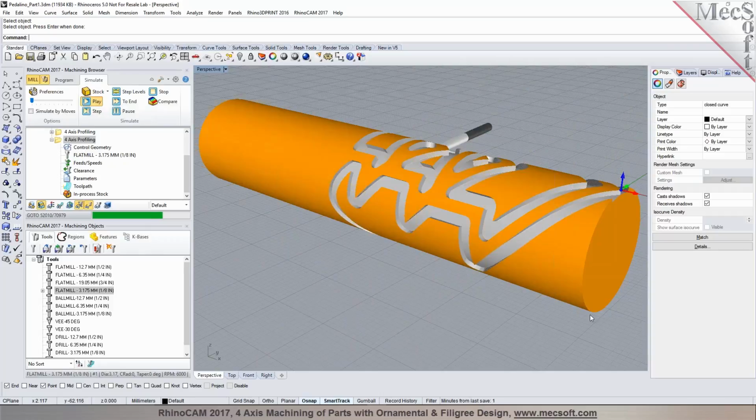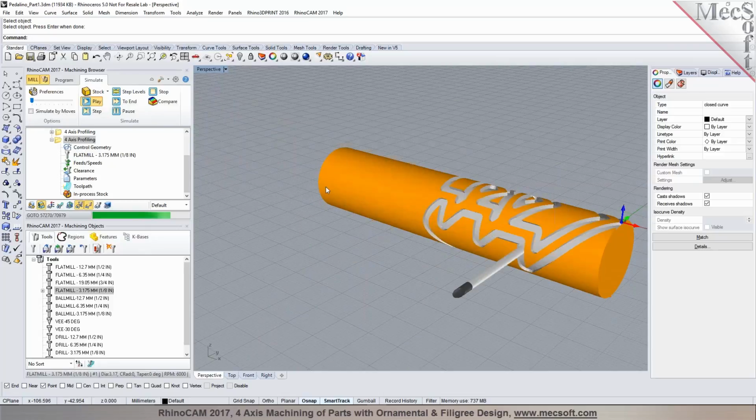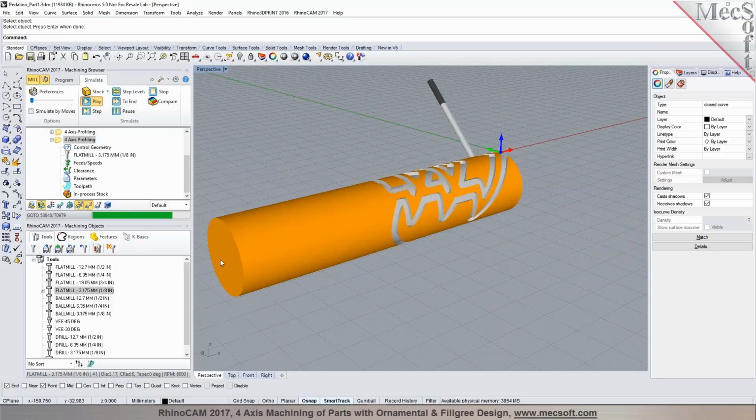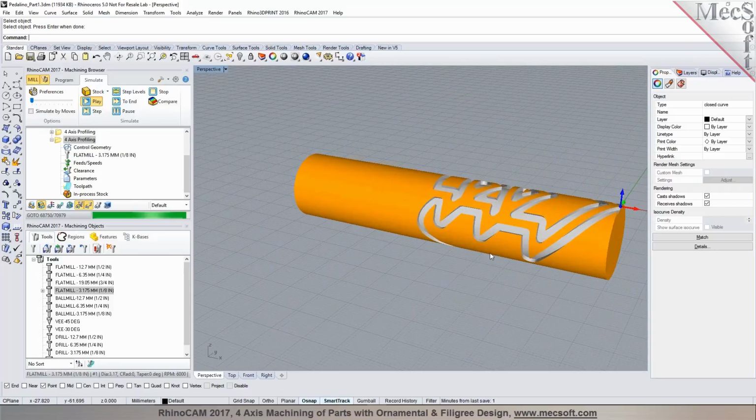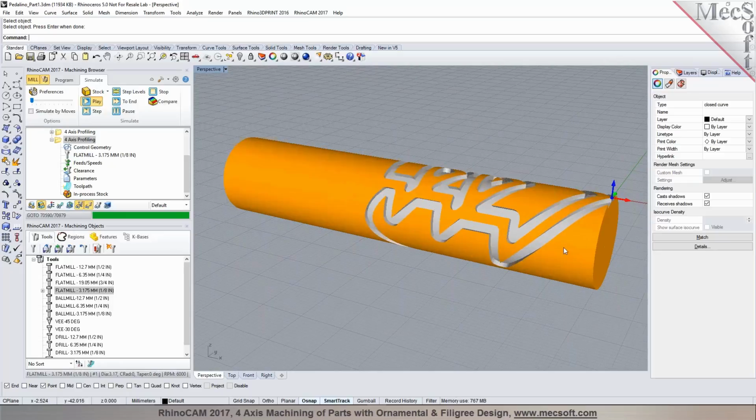Now, for the machine tool simulation, I need to put the rotation center over here on the back of the chuck, and then I would probably have to set the work zero to the top. So that's the way I would have to establish that for the machine tool simulation in order to demonstrate that. And I'll show that to you in just a moment.